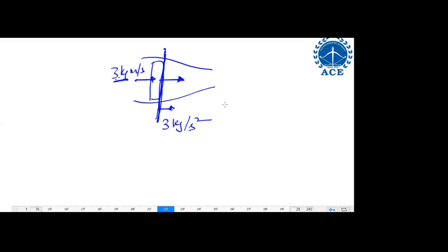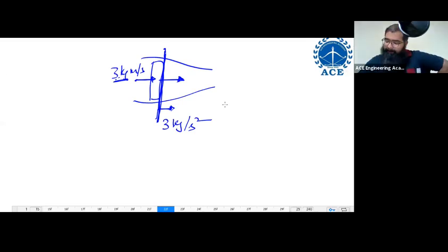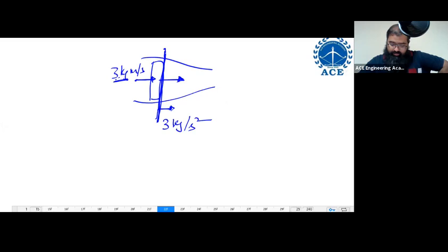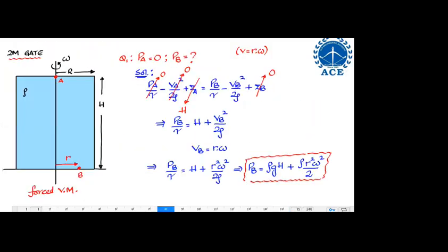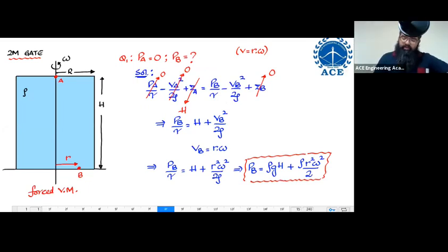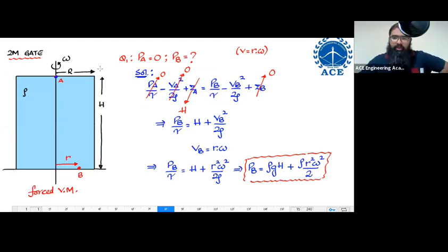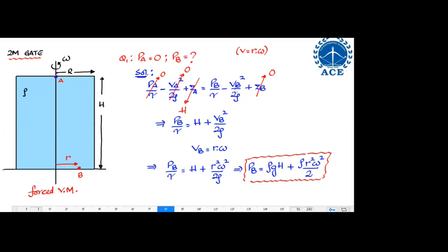Mohammad Jahangir Ansari. Good morning, sir. Sir, I have a doubt on slide number 8. How is velocity VA equal to 0, sir? See, if you are rotating something, the value of velocity has to be equal to radius into omega, r into omega, right? Yes, sir. Now what is the radius of point A? 0. So r into omega is 0. Okay, sir. I think it is open to atmosphere. At this point it is open to atmosphere. That's why it is 0.